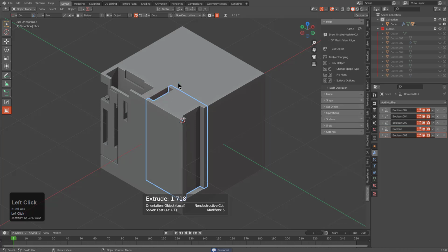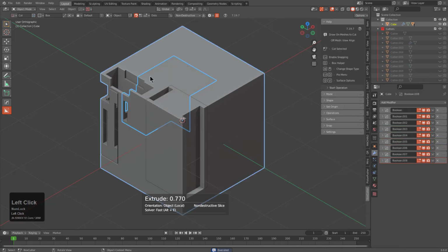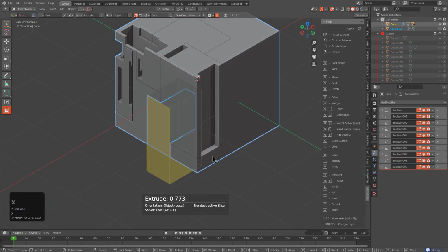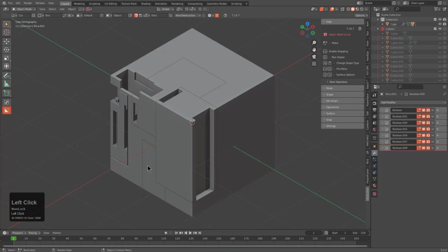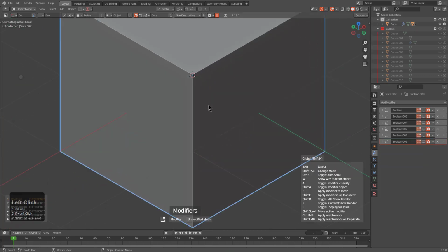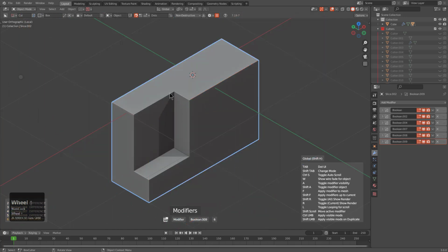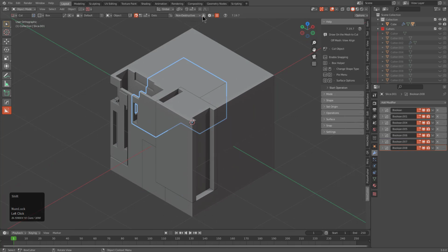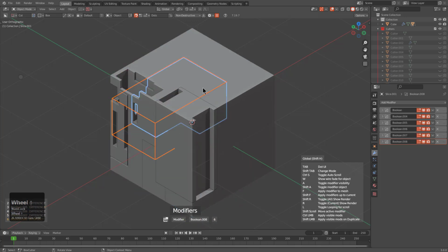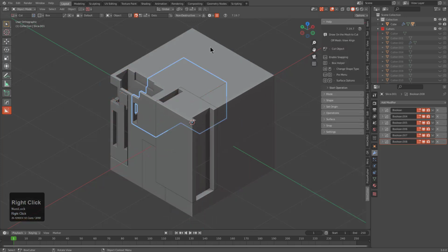Another thing is that you can use this with a multiple selection. If we slice this area off and slice this area off, we can select both of these pieces and shift click the Boxcutter Smart Apply. If we take this in local mode, we see that only the pieces relevant to this object's particular form are kept. In fact, it could be a little bit more strict with what it removes, but it is definitely an improvement in the right path. Let's check this one. It looks like we could hit it one more time. Now whenever we scroll through it, we see that we only have the booleans pertinent to this piece being formulated in the way that it is at the time of being sliced. So hopefully users will take advantage of this in the future.